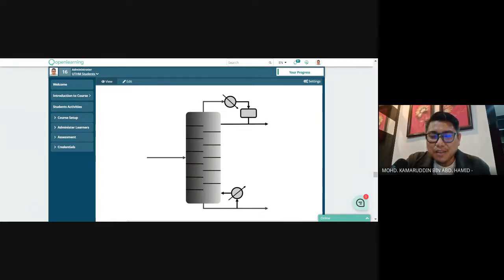Okay. Jangan sekali ingat, don't ever use distillation column if your stream contains non-condensable gas. Memang saya bantai korang terus. Fundamentally, that is wrong because you cannot condense that non-condensable gas. Macam mana you nak pakai distillation column? Okay, there is one condition yang you tak boleh pakai distillation column, when you have a non-condensable gas in the feed. Okay, take note dah.